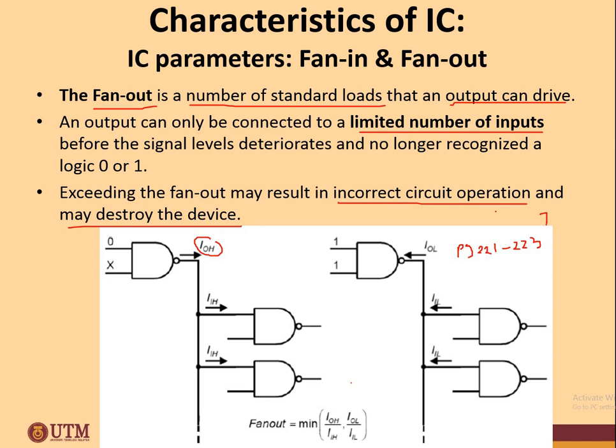This one is for TTL. Your IIH is 40 microampere, and your IIL is negative 1.6 milliampere.